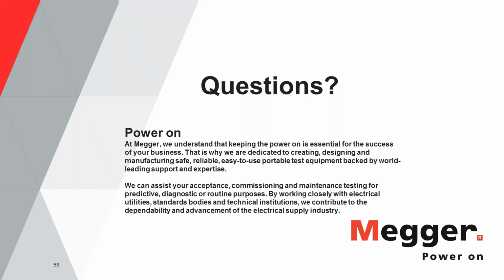So it would still be a valid test, and just as you said, if you don't have a big enough field test set to get that current, then you'll obviously need to reduce the instantaneous pickup. The ideal thing is to keep it as close to what it would be set at when it's in operation. But if it's not possible to achieve that level of current using your field test set, then you will need to reduce the pickup to a smaller value.